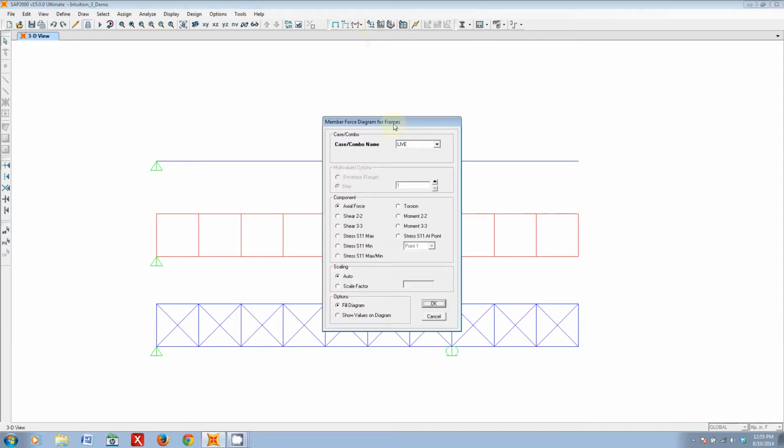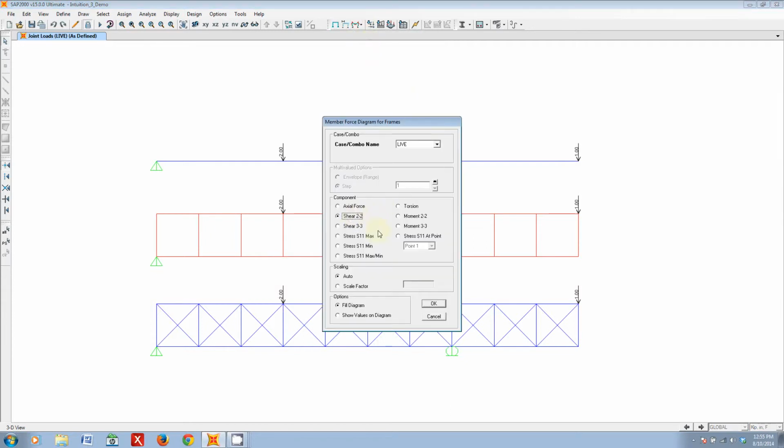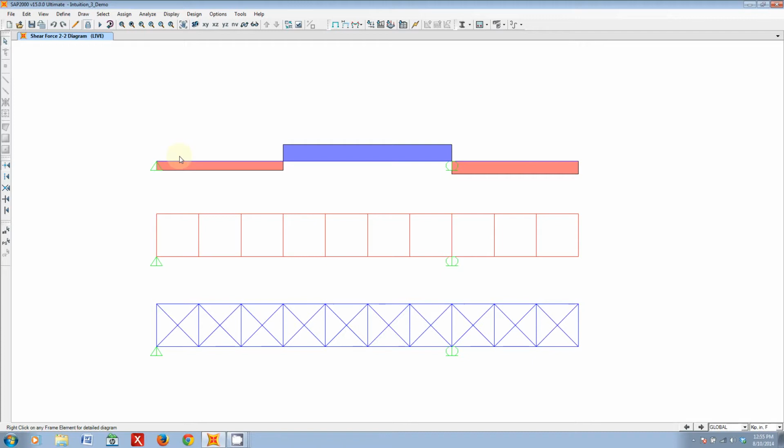Okay, now the last example. Let's check out shear force, but first, actually, I'm going to show what the actual loading is. It's basically kind of like we have a simple span with a cantilever on the end. You can think of this kind of like our bridge from 2013, where we pretty much had this little nice cantilever with a load on here, and then we have a load in the middle backspan location of the bridge. So our shear in the bridge is going to look like this. It's going to be negative, and just jump up to pretty big and positive, and then it's going to go negative.